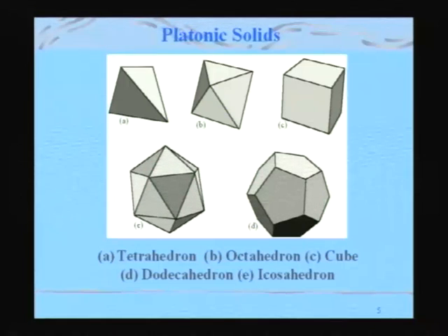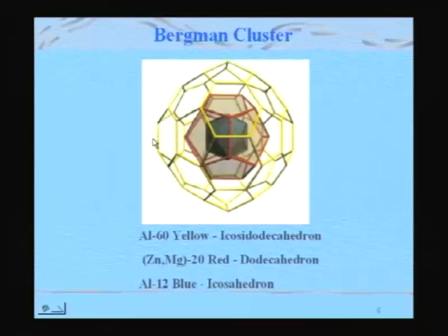a normal cubic structure, when I am talking of various planes, I talk of HKL, 3 indices. If I go to a hexagonal, I go into 4 indices. If I talk in terms of quasicrystal, I have to have a 6-index system. 5 indices for each of these pentagonal corners, 1 for the C axis. But in principle, one can convert these 6 indices into 3 indices, like the way we convert the 4 indices in a hexagonal to a 3-index system. So one can convert these things, and that's how people talk in terms of quasicrystallography.